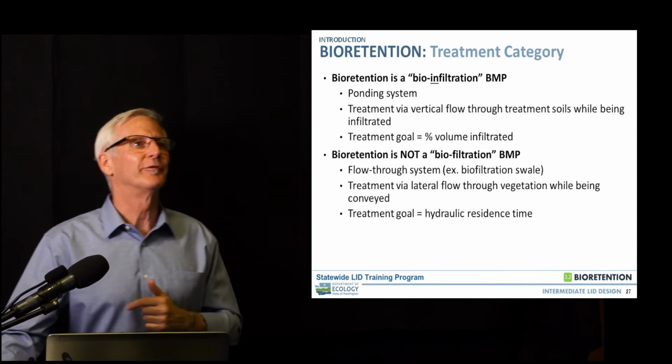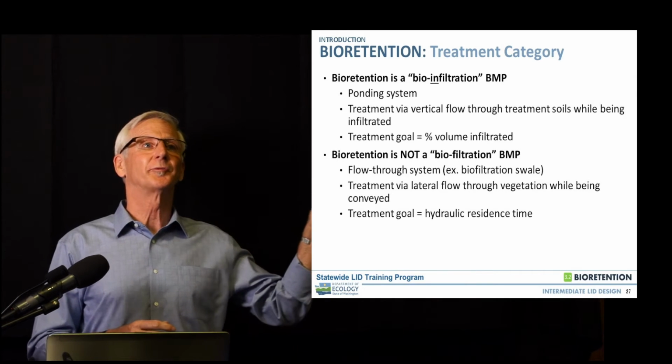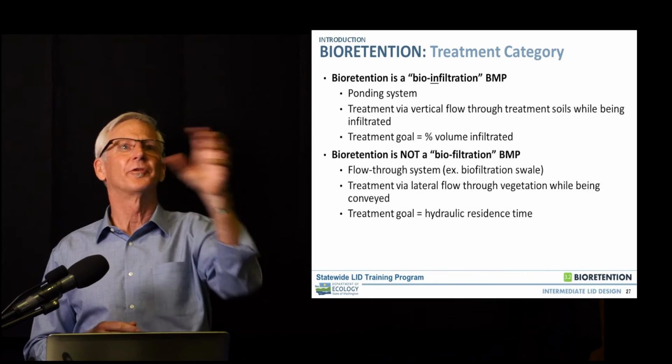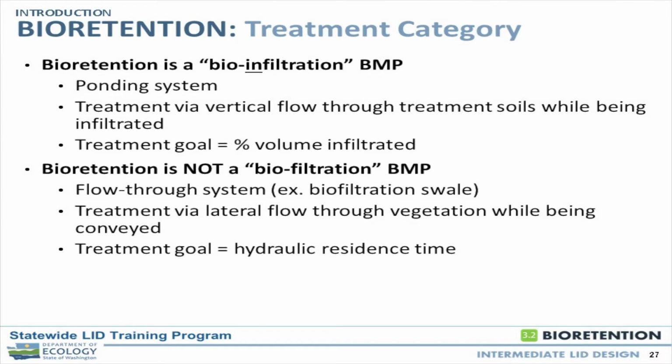Bioretention is not biofiltration or, say, a bioswale that is primarily surface flow through vegetation. It's rough vegetation. There's filtration through that swale. Surface, horizontal flow as opposed to vertical flow. That's a big difference between bioretention and biofiltration. There, we primarily think about treatment goals and our modeling in residence time.